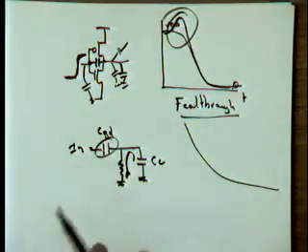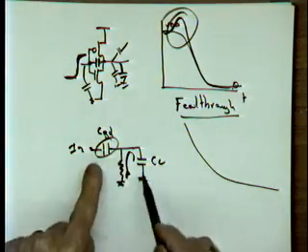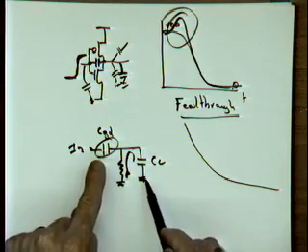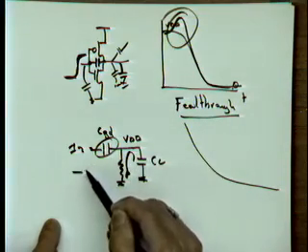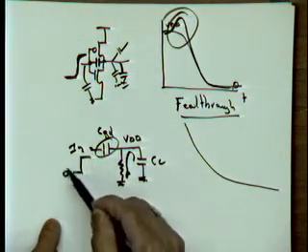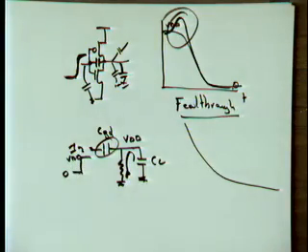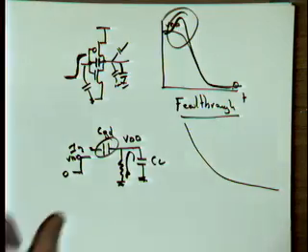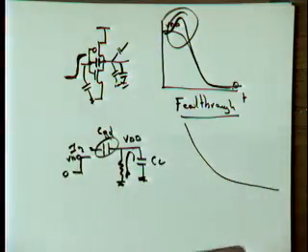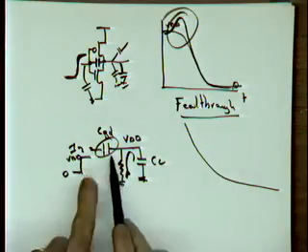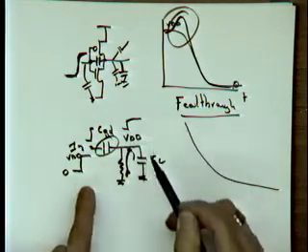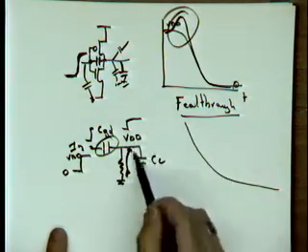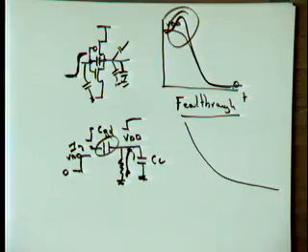However, this capacitor plays as well. This is a capacity divider, right? Two capacitors. If I now apply a step here, this is at VDD. This node initially at 0 goes in one step from 0 to VDD. You can see capacitive coupling is an instantaneous thing. You have two capacitors in series, and I apply one voltage, and the other guy is going to follow right away. So I move this node up, this node is going to try to follow. Not as directly, but it's going to be a divider sitting in between those two steps here.